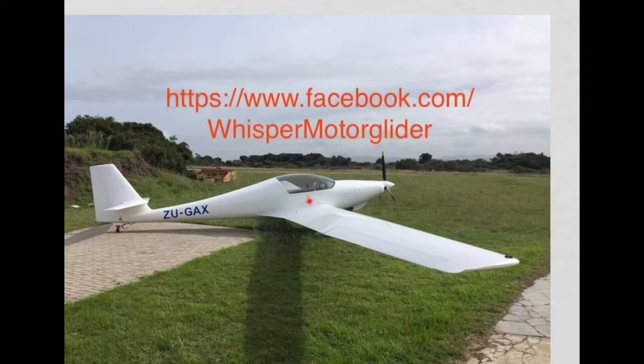Now, the joystick is connected to a push rod which goes all the way down the wing here, and you can't see it, but underneath the wing is a little hollow, and in there is a bell crank exactly like the one we have in this problem, which changes the force from the pilot, which is aligned with the wing, to a force in this direction, which operates a short horn under the aileron and makes the aileron go up and go down to control this aircraft.